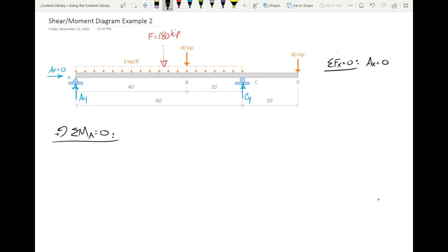Right? So if you have, let's say, 200 pounds per foot, and this dimension is 8 foot, just think about it, it's really just some common sense. If I have 200 pounds per foot over a distance of 8 foot, that's a total load of 1,600 pounds, right? I promise it's not a trick. All we're really doing is just saying, okay, what's the area under that load? That's basically all we're doing.